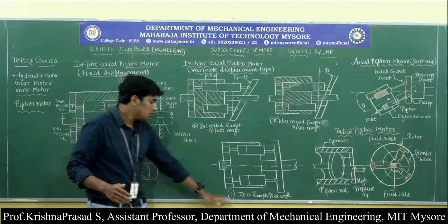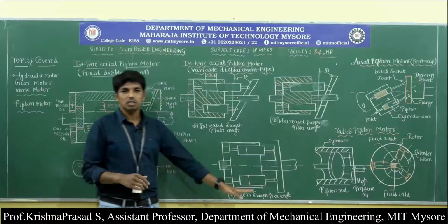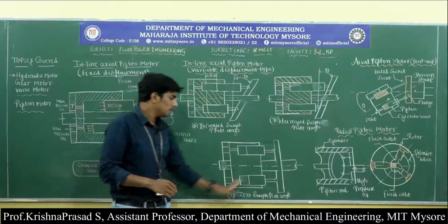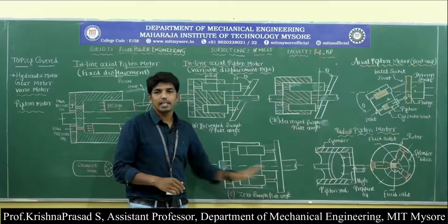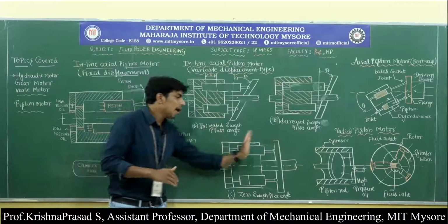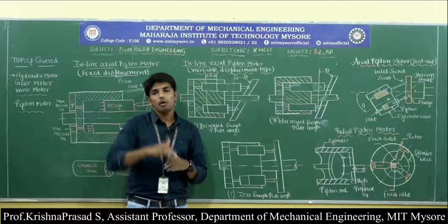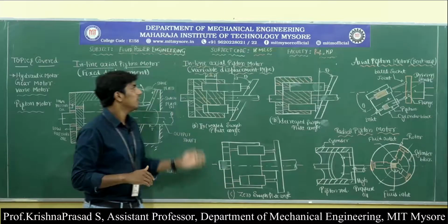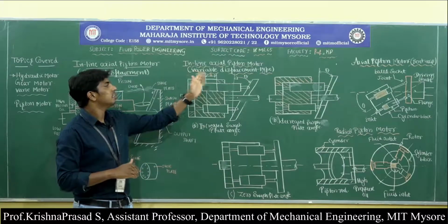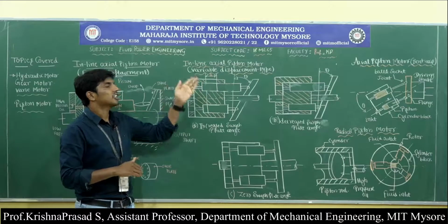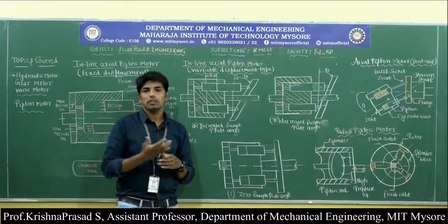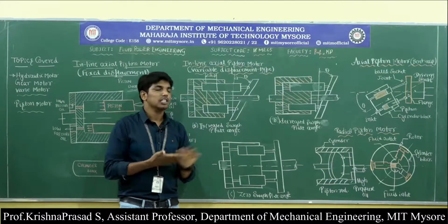And the next one is called zero swash plate angle. In case of zero swash plate angle, there is no speed and torque achieved. But a minimum angle should be provided in order to operate the hydraulic motor within the operating limits. So that is regarding the three cases of the variable displacement type of inline axial piston motor. First of all, why do we need the variable displacement type?